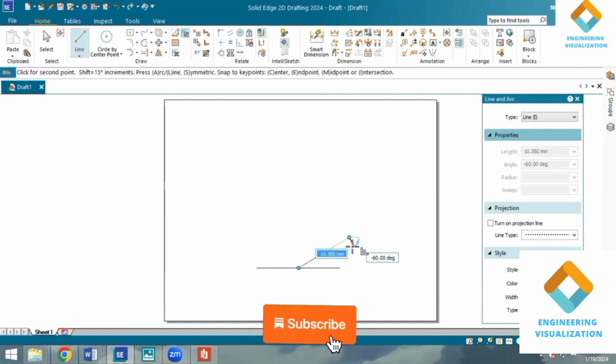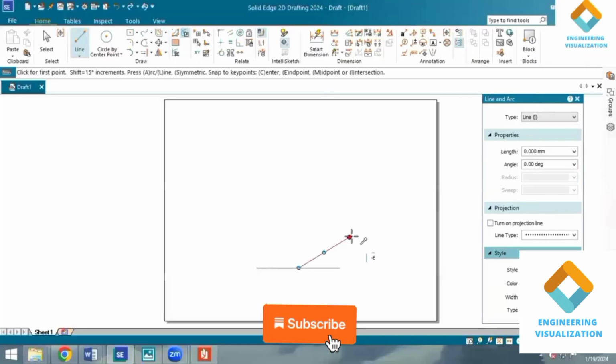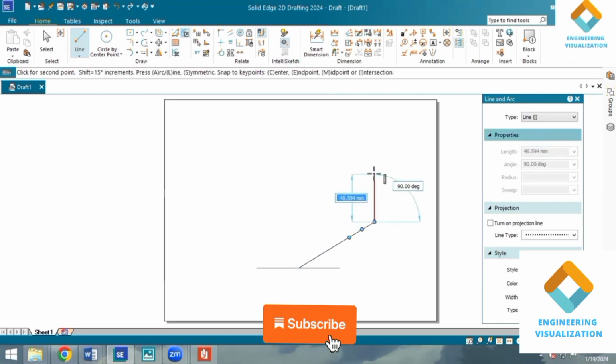Okay, first I'll be constructing a rectangular block. So here the rectangle block having base sides 30 mm, 30 degree, and vertical edge 60 mm, angle is 90 degree. Again length is 30, angle is minus 150, and then vertically downward is joined with a length of 60 mm.